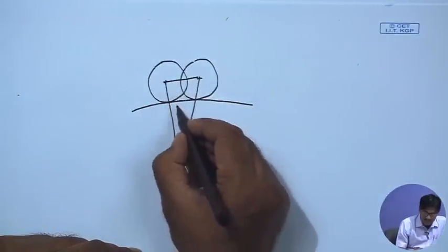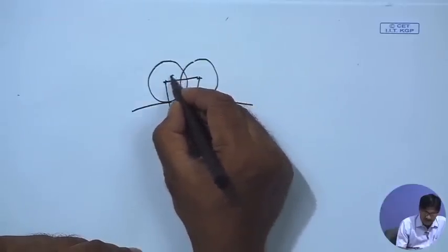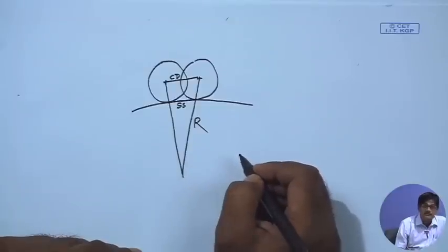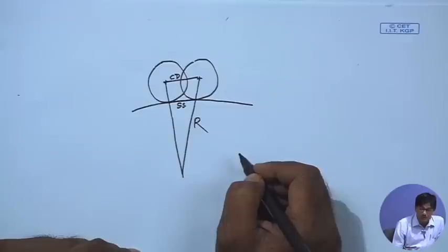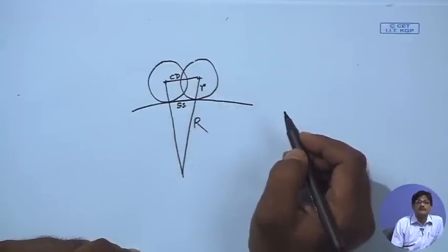So, we are basically saying this is the side step and this be the center distance and this be big R, the radius of curvature of the surface orthogonal to the cutter path, and this is the radius of curvature of the cutter.